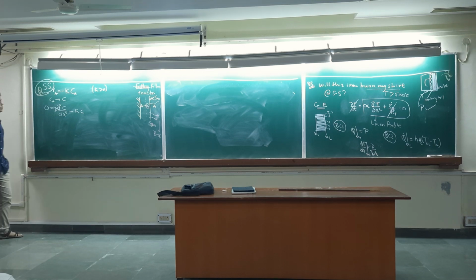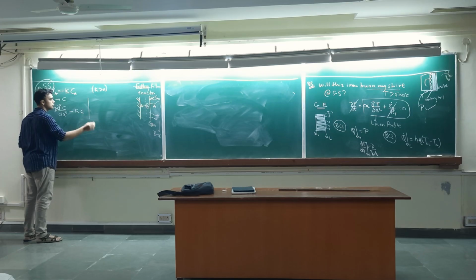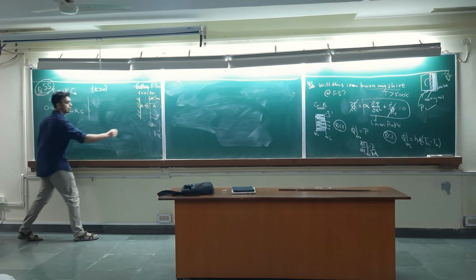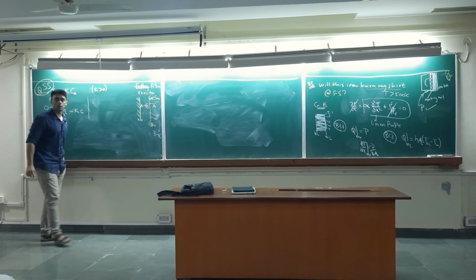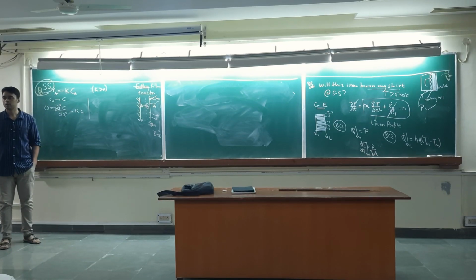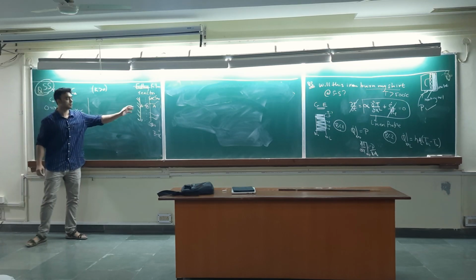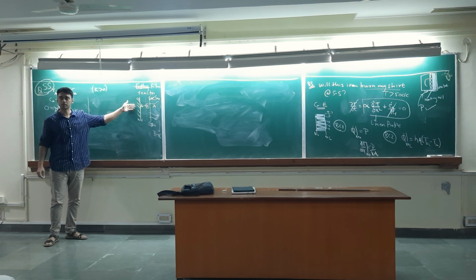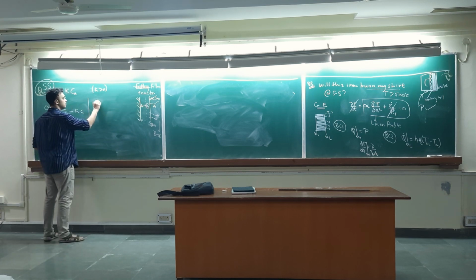Now we have to write down the boundary conditions also. What is the boundary condition at x equal to 0? Dirichlet-Neumann mixed. This is a solid surface which is not allowing A to pass. So the flux of A through this is 0, no flux. So I should write this J is equal to 0.